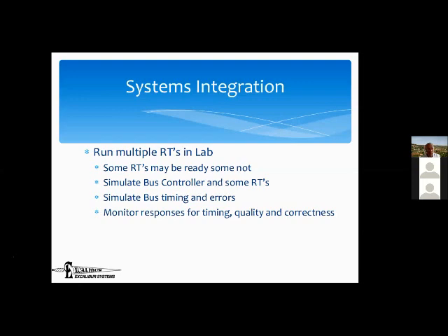And you may want to monitor, let's say the bus controller came in and not necessarily all the RTs. The bus controller is responsible for efficient use of resources. So you can monitor everything it's putting out, check the data that it's giving to the various RTs, and check the timing, make sure that it's not trying to stuff 3 seconds worth of communication into a second, because it's not going to work. So this monitor can tell you all of that.